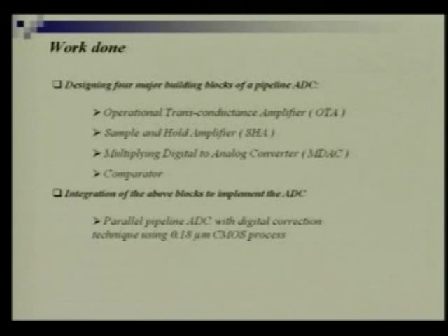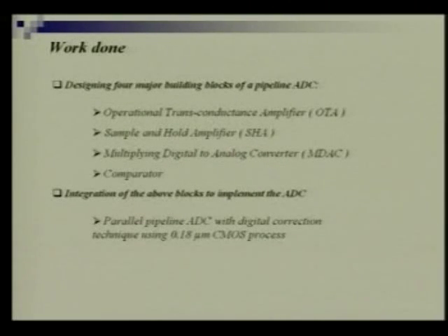Once you do the simulation, if the simulation is going okay, then you can go ahead with the layout. Once you do the layout, according to the design rule, you are to pass it through the DRC, that is the design rule checker. Then you are to go ahead with the LVS, that is the layout verification with the schematic: the schematic you have used and the layout you have done, whether they are matching, that part should be taken care of by the LVS. Then if it is okay, you can pass it. Then you can integrate those blocks to get the final ADC.